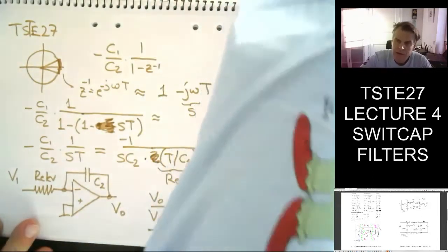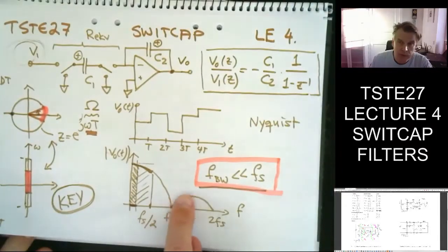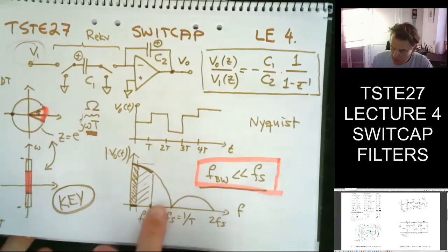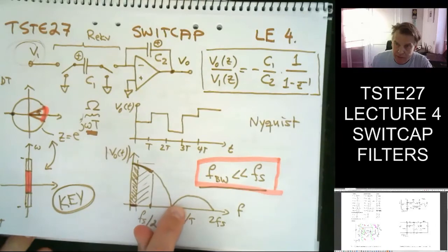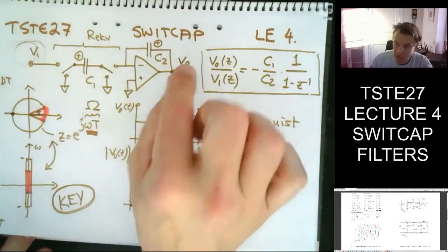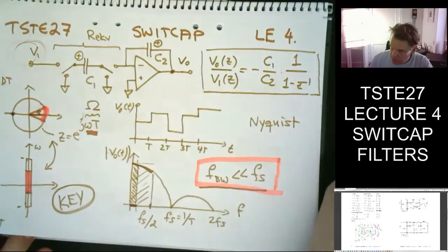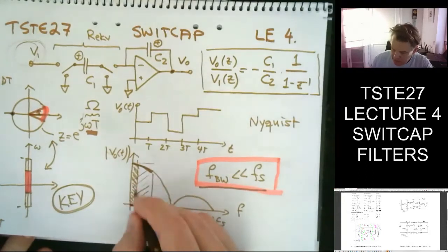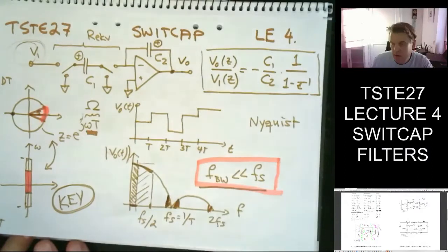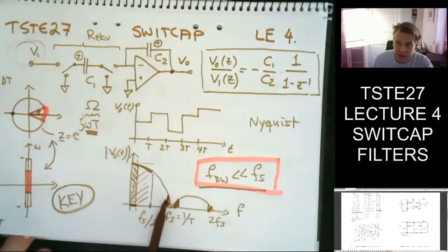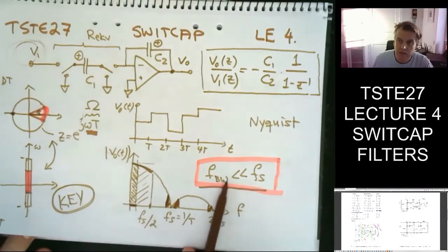Of course, we might need some filtering to filter out components here. This frequency domain will replicate itself if I measure with the spectrum analyzer on the output. I will also see some replicas of this happening around multiples of the Fs. But typically we have quite high attenuation due to this requirement.